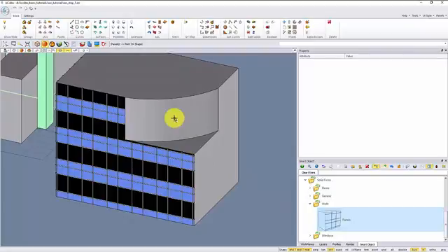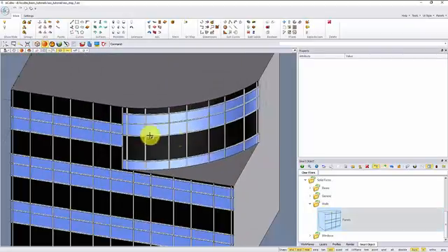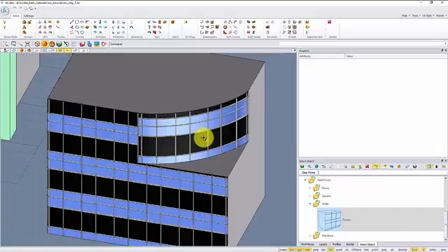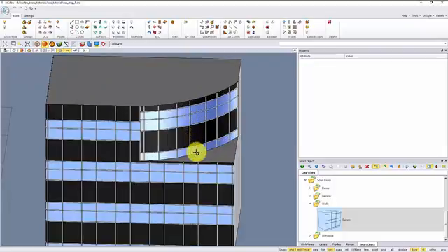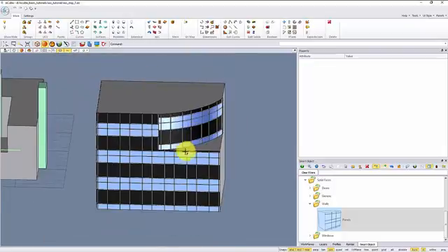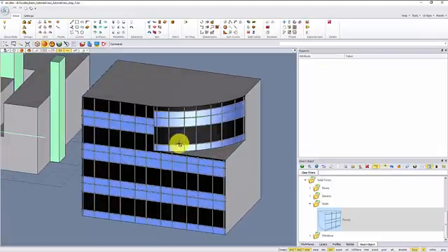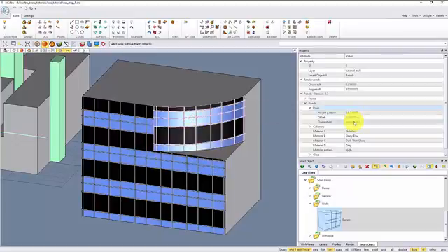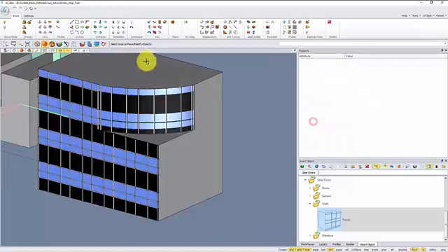If we drag and drop the smart object over this curved face, we can see how it works even for curved surfaces. And now we see what happens here. Since we have defined the panels that grow from bottom to top, these panels here do not match anymore. Well, we can fix this by splitting the bottom one in two parts, or we choose a top-bottom distribution for both faces. What happens if we have a hole in a face?